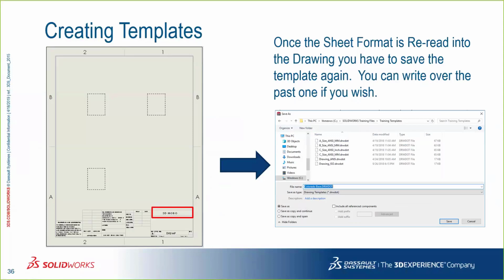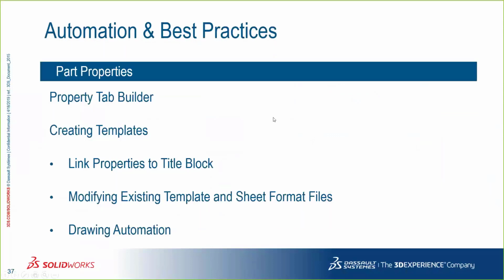It sounds like a lot of work, but we get this call a lot. It's because, hey, I just did this. Why isn't it working? Well, you have to open up your template, copy in or reread your sheet format, then resave your template over itself. Then it will work. All right, so let's dive into that so I can show you guys how that works out.